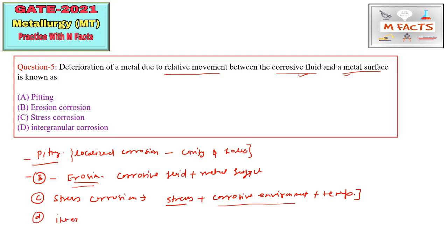This is a special type of corrosion which happens in stainless steel, generally 18-8 stainless steel, in which a chromium carbide layer precipitates on the grain boundaries. This is due to excessive residual carbon in the stainless steel, or prolonged exposure to elevated temperature.